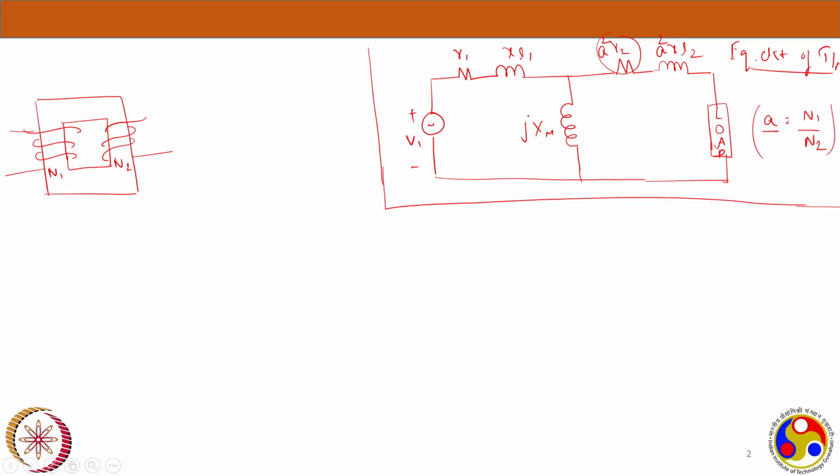The important thing is linkage. Now, flux and flux linkage are two different things. Flux will be created whenever you pass a current through the coil. Now, when the flux links with the other winding, when it relates with the number of turns of the other winding, then we call it flux linkage. So whenever flux linkage happens, definitely a voltage will be induced. So now we will see what the inductance of a coil is.